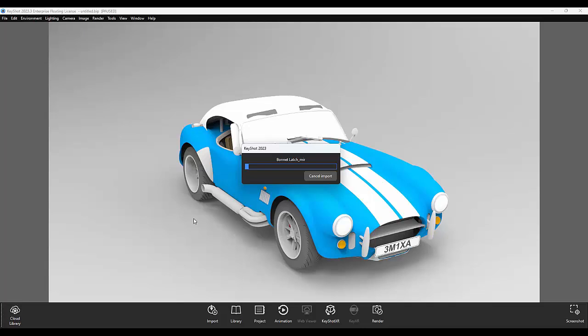So from here, it's not going to replace anything, or remove any progress that you've made. So let's say you've been working on this render for quite some time, you've made a change to the model, and you want that to be reflected in your render. This update geometry will only ever update the actual CAD model rather than any materials or textures or anything else you've applied.